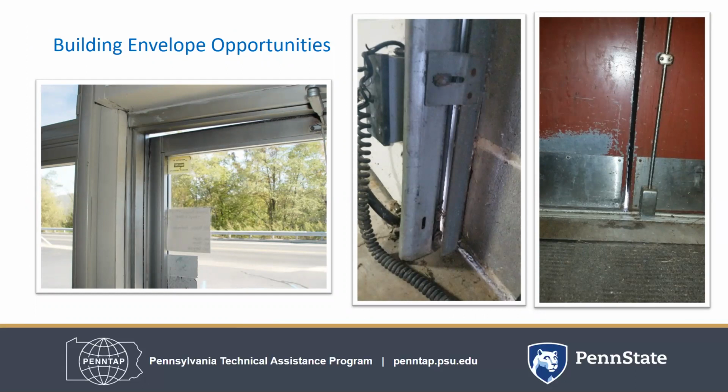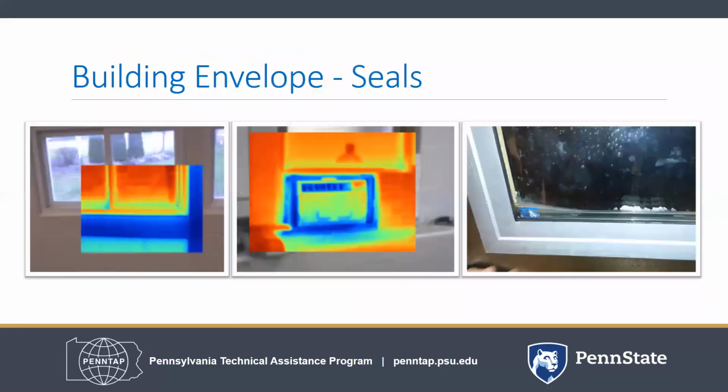Perhaps the main entrance of your building needs adjusting, or the garage door for your deliveries has huge gaps where you can see daylight shining through. Maybe the double doors to the maintenance building need a new seal. These are a few examples. Here are some more. Here, using the infrared cameras, we can reveal the cold air infiltration around the windows and around an air conditioner.